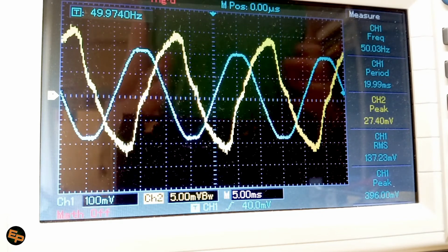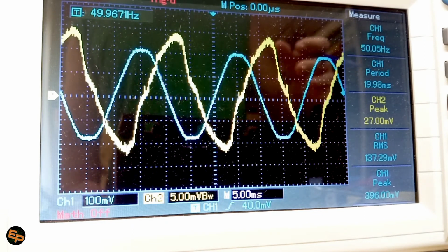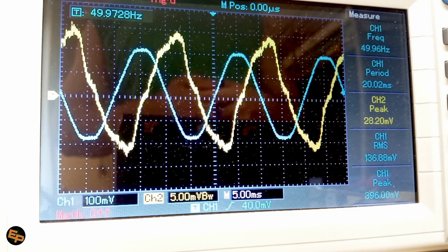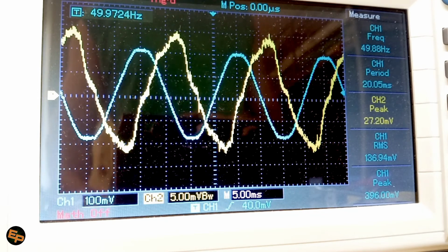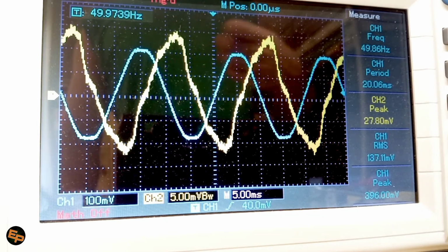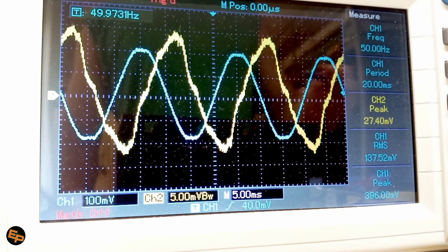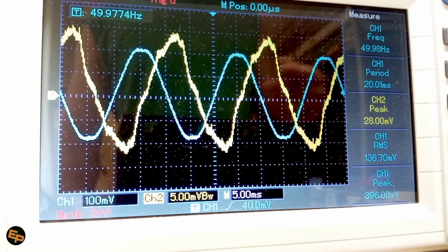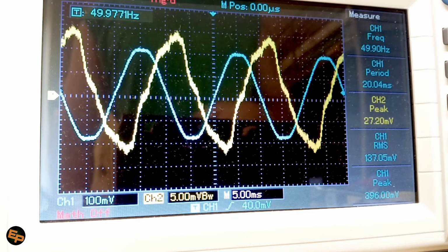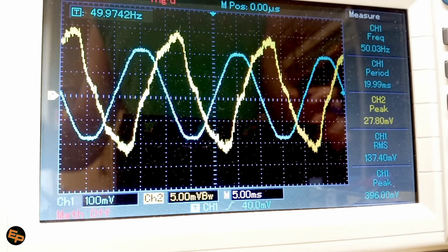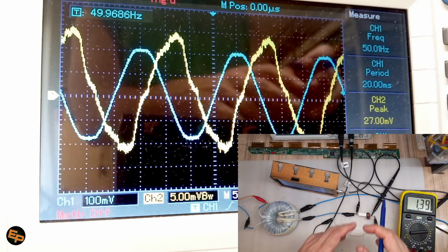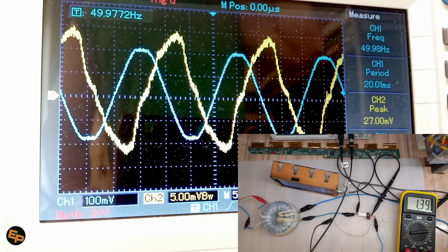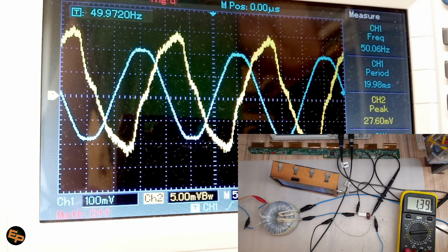By the way, the increase is not linear. The transformer's response is not linear. Sadly, it's a little bit exponential. The more current we draw from the initial circuit, the higher the voltage grows, but not linearly. At double the current, we get more than double the voltage on this particular transformer. Again, it most likely matters a lot how I've built it. Anyway, it's good enough for me because, again, I don't plan to use it for some precision measurements.